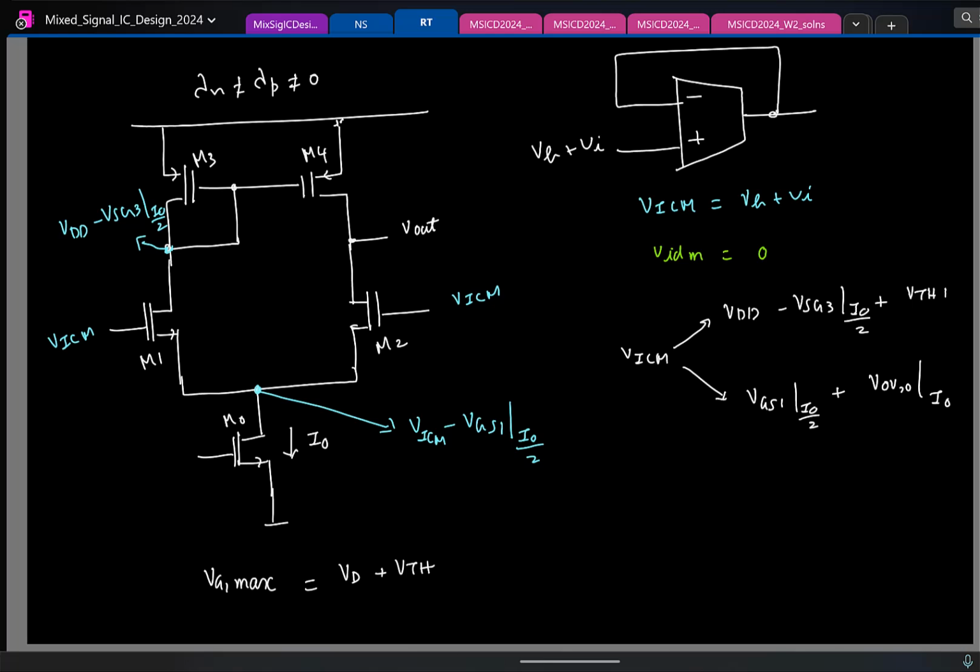So now you tell me, if I keep reducing the output voltage, which transistor can go out of saturation? I have loosely, this potential is connected to only two transistors. So logically speaking, if something changes, only these two fellows might have issues. Now if the drain voltage is dropping, the PMOS transistor, will it have any issues? No. So we'll have issues only for the NMOS.